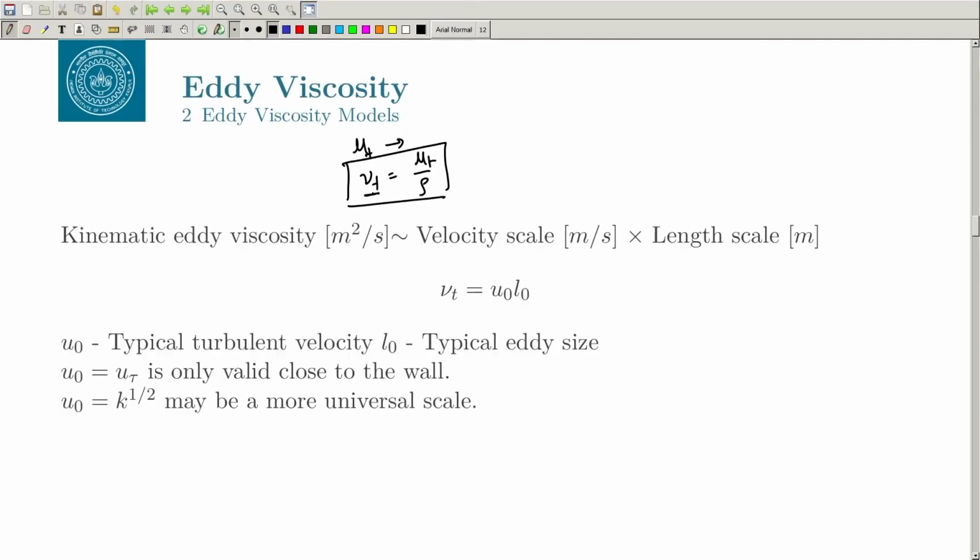They are all based on this eddy viscosity model, and this works quite well for a wide variety of flow, and it is much cheaper than the Reynolds stress model, because for the Reynolds stress model, if you want to derive the dynamical equations, you need at least 6 dynamical equations, right. So, for each of the stress terms, okay, and that will be very, very expensive. So, let us see how we can find out this mu T.